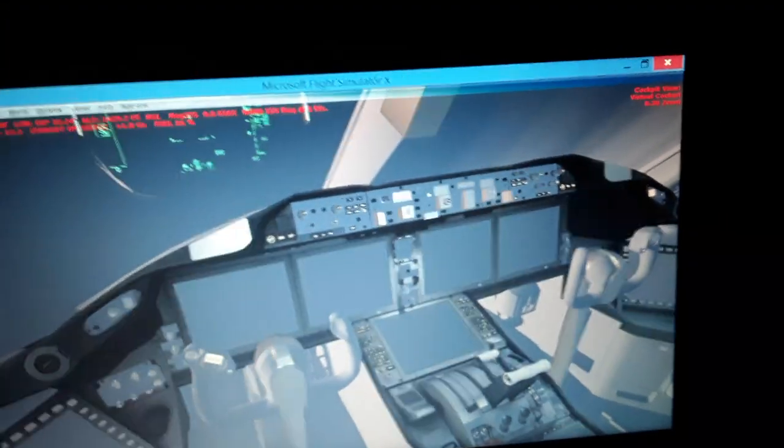So for instance, here we're gonna have the horizontal tail trim stabilizer set for takeoff, the pitch trim calculated automatically using the flight management computer, using the takeoff speeds, the aerodynamic chord position, the center of gravity, as I told you, and the flap settings for takeoff and the runway length. So we're gonna have the pitch trim set automatically, like 4.25 degrees.